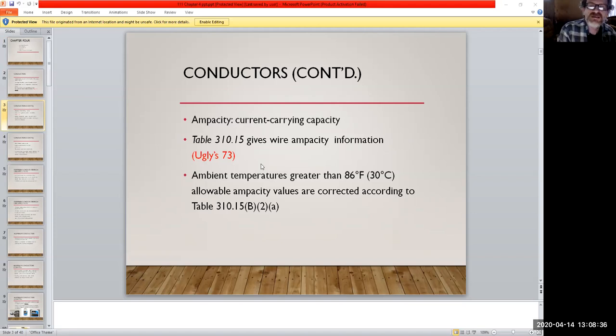Hopefully that makes sense. But they have it all set up for you in the charts. You can look through and see what your temperature is and go ahead and size your wiring accordingly. And of course, it's larger sizes, so you're going to be increasing your prices, right? Larger size wire is going to be a little more expensive. Just something to remember.